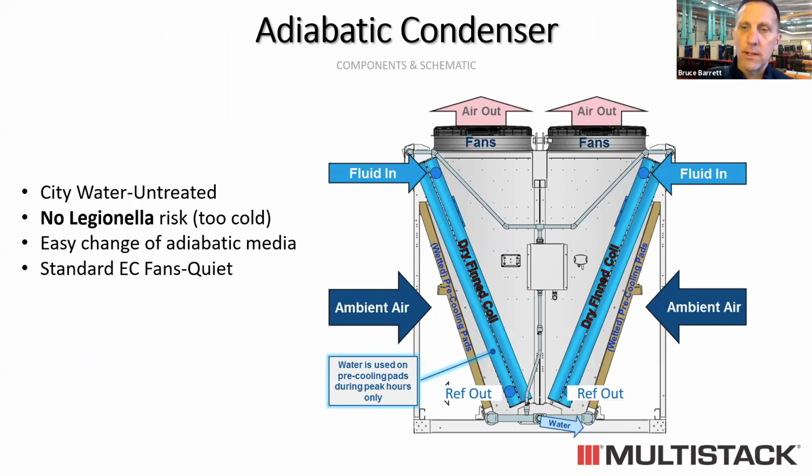There's no Legionella risk given that water temperature is too cold for it to grow. So for the concerns of towers that need proper balance of chemicals and the Legionella concern, that's been eliminated. These are quiet condensers. Single condensers can go up to about 300, 350 tons for a single machine.